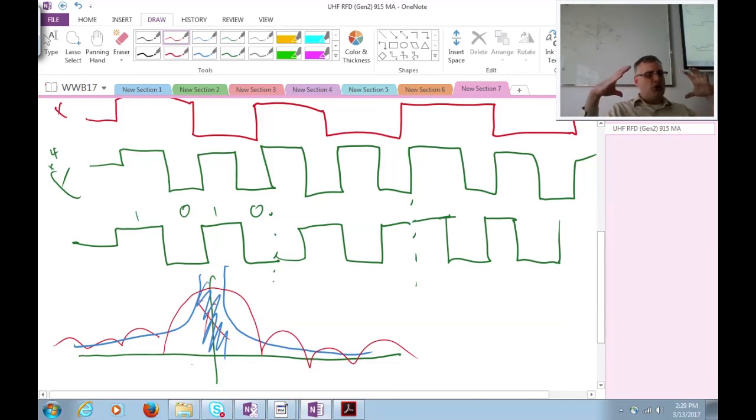If I get too much noise or interference in a conventional wireless system, let's say I'm transmitting 1s and 0s across the radio link in a Bluetooth link or a Wi-Fi link, and I had complete control over the protocol and found my link was too noisy, what could I do to increase the detectability? Well, remember, in a thermal noise limited system, if noise is my limiting factor, what I can usually do is just slow down my transmission.